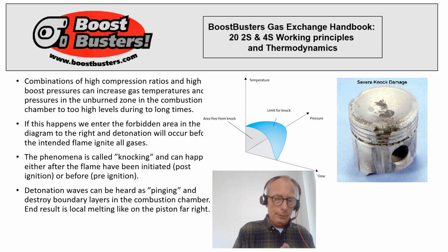Detonation or knocking can be pre-ignition, where this detonation process starts before the flame is initiated, or more commonly post-ignition, when the flame has started to propagate, but some small parts of the gas are still detonating. During detonation, we hear a ping, ping noise, which is not so appreciated. That's the reason for the name knocking.